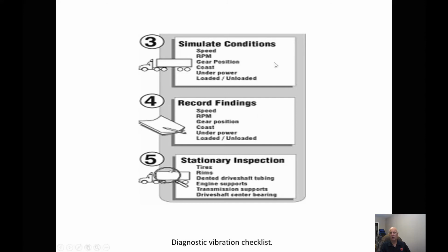Check your tires. We talked about tires that are different in diameters, where again we're allowed to have 3/4 inch in circumference, 1/4 inch in diameter. Is there a rock stuck between the duals? Have we got a U-joint coming apart? Have we got a yoke nut loose? Is the drive shaft being damaged, or out of phase? All these things we want to take a look at before we carry on.